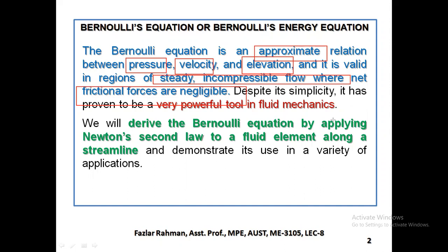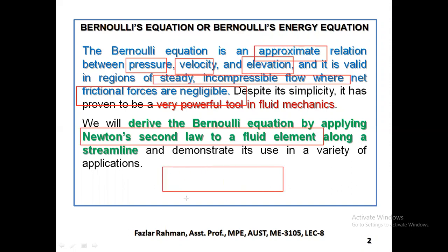Okay, and how will we derive the Bernoulli's equation? Again, we'll apply the knowledge of your engineering mechanics. That means we'll apply Newton's second law to a fluid element, and that fluid element is flowing along a streamline in a flow. Then we look at how a fluid particle is flowing from one location to another location. Either somebody is pushing from behind, or what is the property in the water in the river